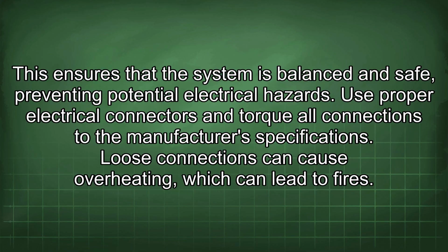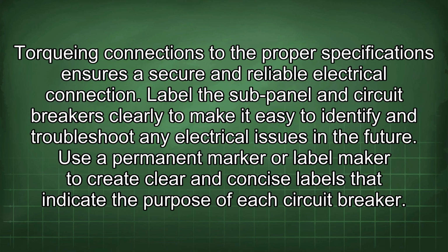Use proper electrical connectors and torque all connections to the manufacturer's specifications. Loose connections can cause overheating, which can lead to fires. Torquing connections to the proper specifications ensures a secure and reliable electrical connection.